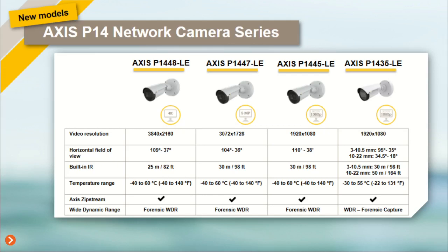And the settings per stream are different. One is normal lighting condition, one is a low light condition, and then a high light condition. We use those streams and put them together live, creating the WDR picture. Because we have a higher capacity on our processing chip, we can do this WDR and make sure that it doesn't increase the latency too much. Of course, there's always a little bit of latency. Hopefully this answers your questions a little bit.